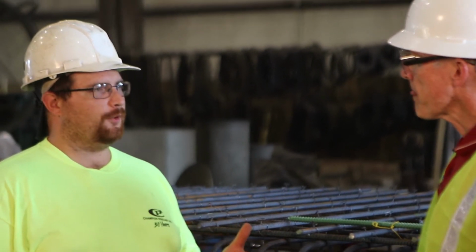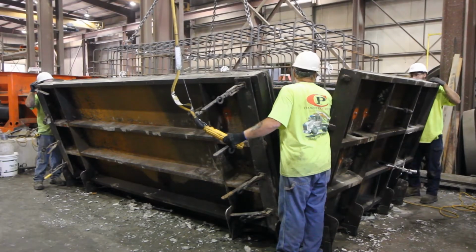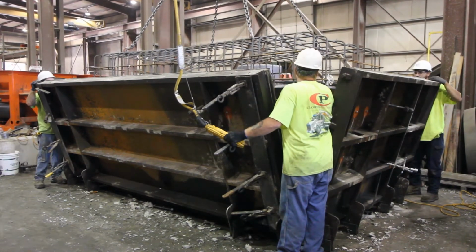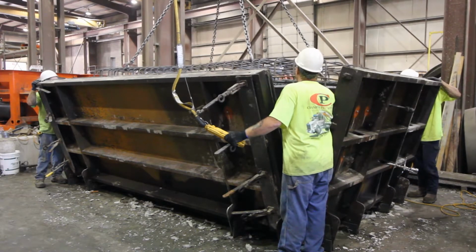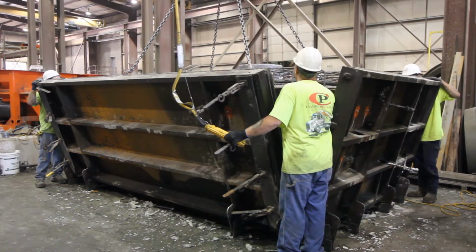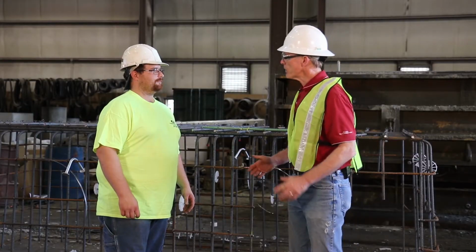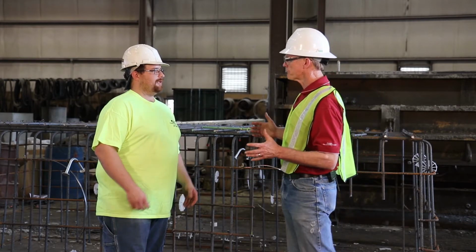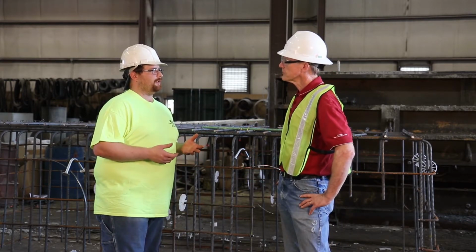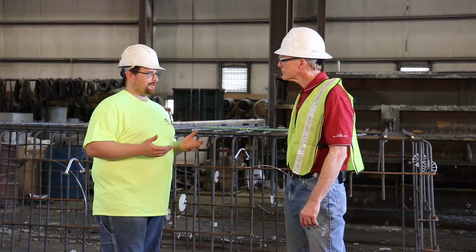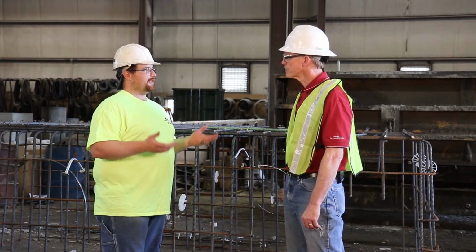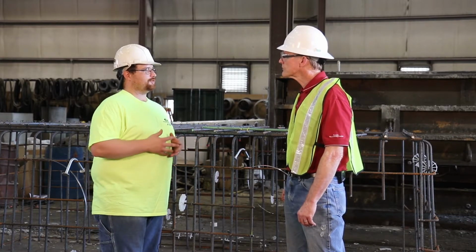Well, the most obvious way you can tell whenever a cage was not built right is if it does not go into the form easily. If you have to force the cage in, that should tell you some dimension is out of tolerance. A force fit will introduce added stresses into the product after concrete casting and hardening. So Michael, what about cages that are loose fitted? Similarly, cages that are loose fitted, whenever you put them in there and the cage spacers are not in contact with the surface, they too are actually out of tolerance of the drawings.